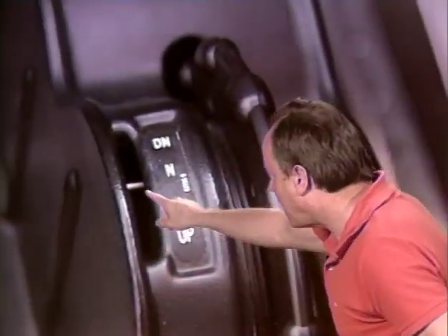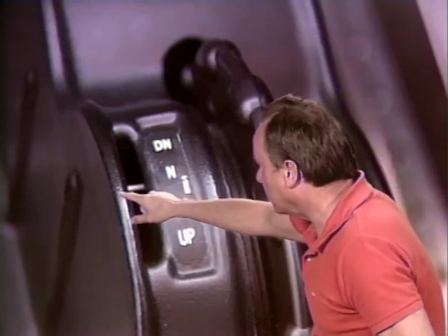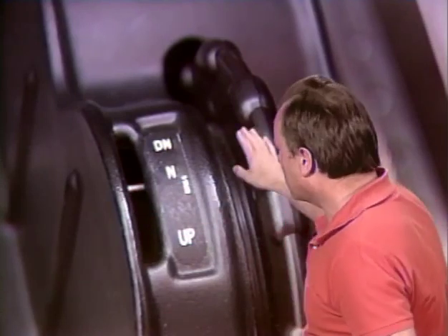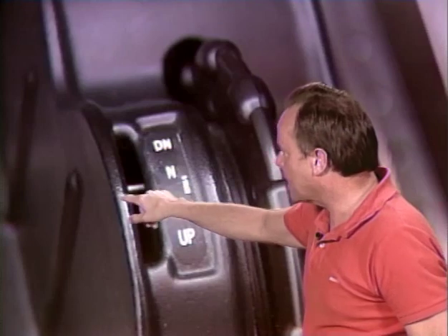Now they want you to know that when you're inside the cockpit and you have flight control trim systems, the controls inside the cockpit must be designed and installed so the pilot can determine the relative position of the trim tab from the cockpit. That's an important thing, and it's got to be accurate. So if you install a trim control inside the cockpit, the pilot must be able to see the trim position from inside the cockpit.